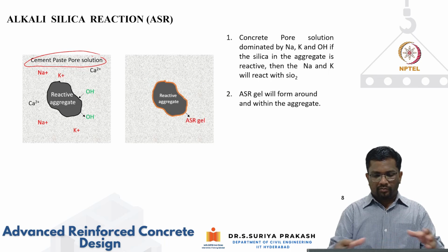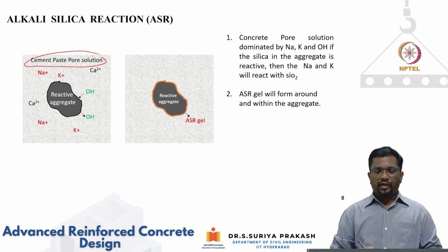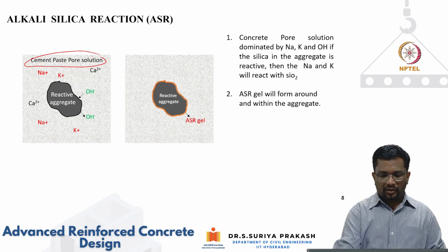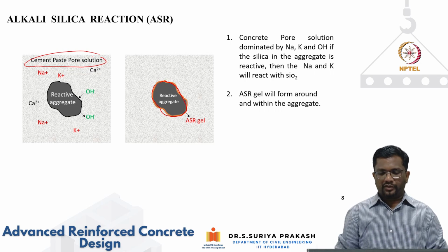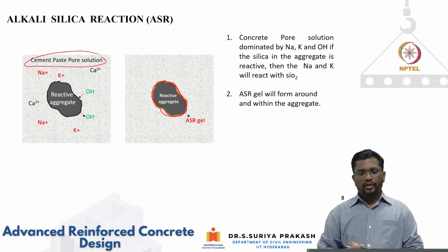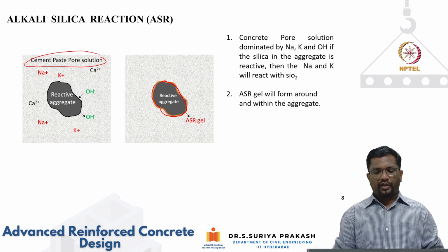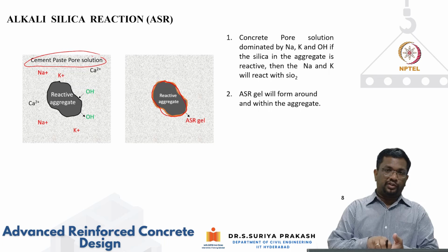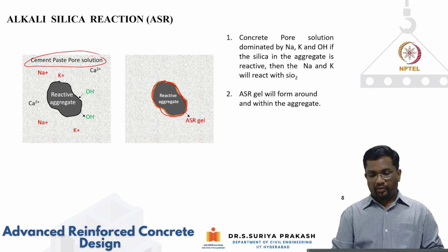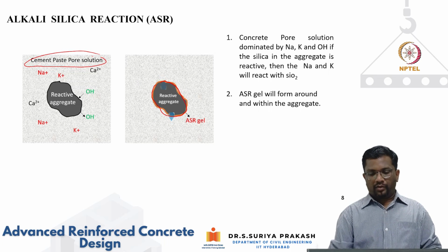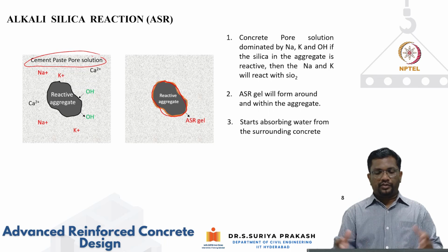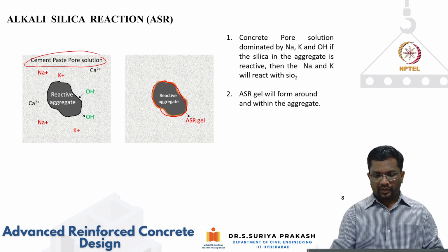So what will happen is all of them will start reacting, and it forms this kind of gel, which is called the alkali-silica reaction gel. It will form around the aggregate, and if aggregates are porous themselves, it can also form within that aggregate.